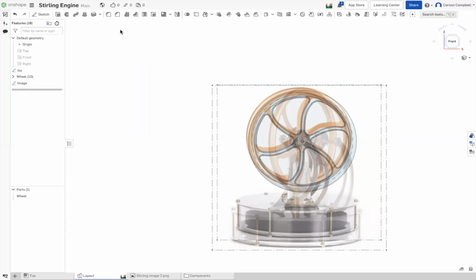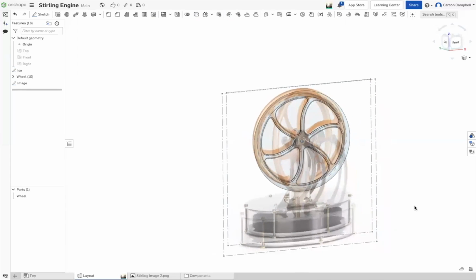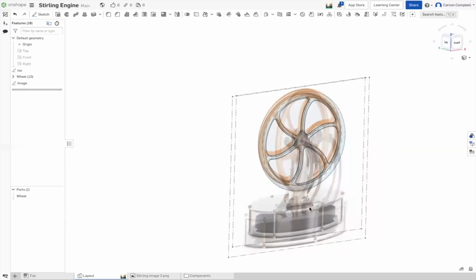What do we want to do now? Obviously, with this bracket, there are going to be 2 of these brackets. Is that what you want to do, design those brackets? Yeah, I mean, that's not too bad. Okay. And then if it's a bracket, do you want to be able to create a flat pattern of that bracket? I guess so, right? Yeah, you do. Otherwise, you won't be able to make that bracket. That's called sheet metal, and in Onshape, we can make sheet metal parts.